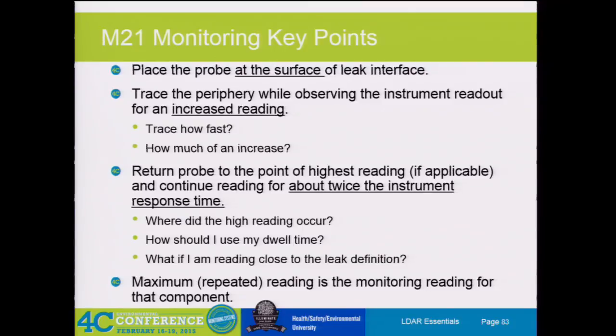It's never going to directly come out and say it, but you have to do surveys on your components, and you're surveying the leaking interface. When you go back to teaching technicians, or you're doing it yourselves, make sure you're spending less time at the least likely place to leak versus spending more time at the most likely leaking place.